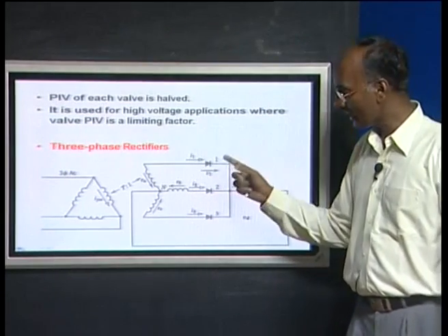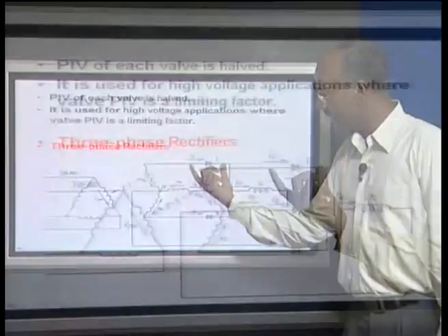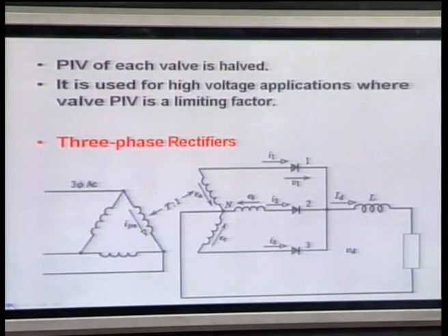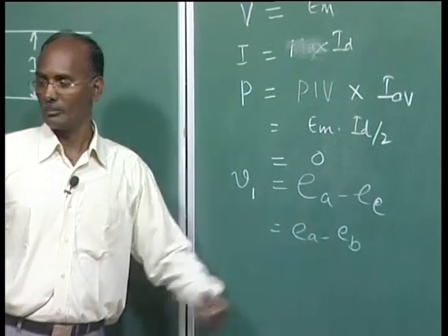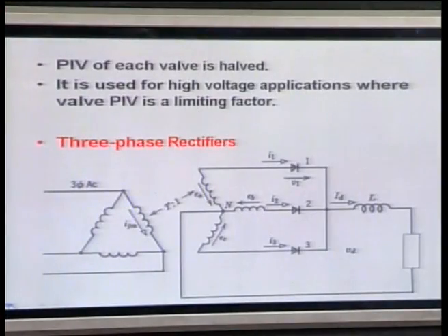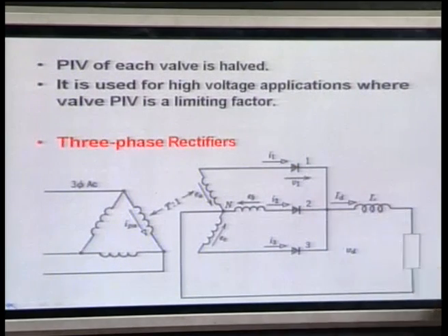So, in that wave shape I said it is going to be here, this is the conducting. This EAC is called its commutation voltage, because it is going to be fired, which means the voltage just here is going to be positive so that it can be fired, that is, once your EAC becomes positive, as you will see from this graph again, because we will be using these things when we go for the bridge converter.